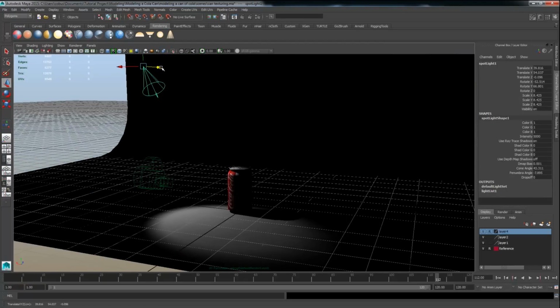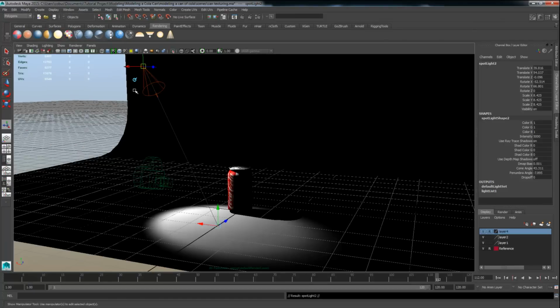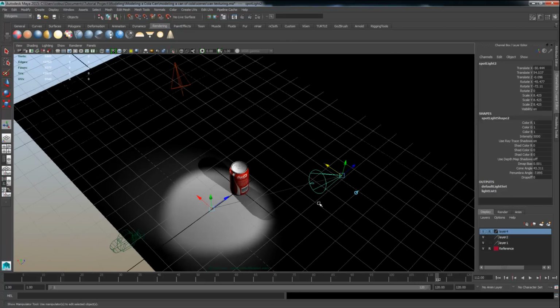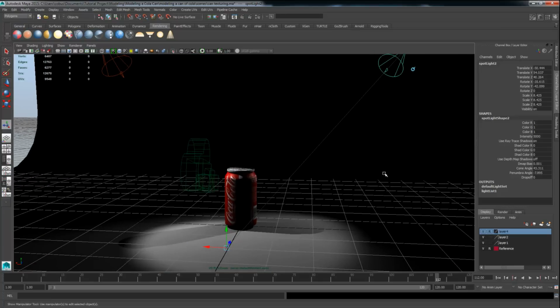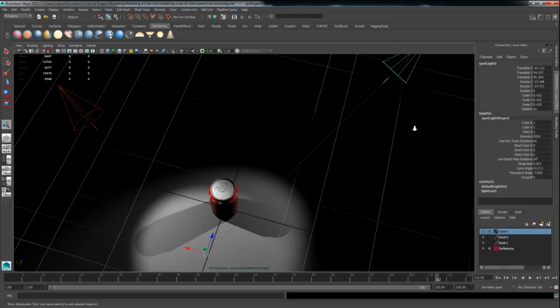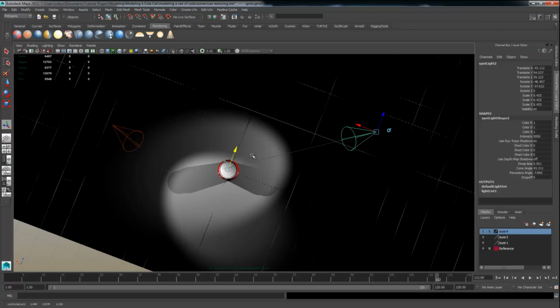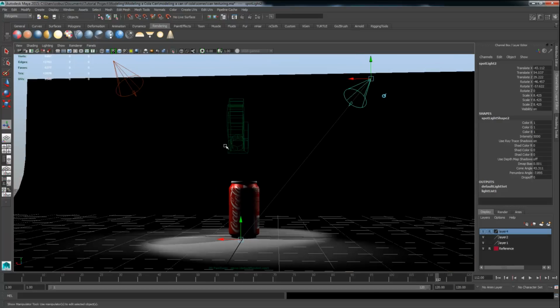So if I move the light off and over, I'm then going to duplicate the light, press T, and then scoot another copy of that light to the other side and maybe pull it back so I have a little bit of a different shadow direction. Something like that. Maybe move it more, and just aim the other control handle a little bit further back.